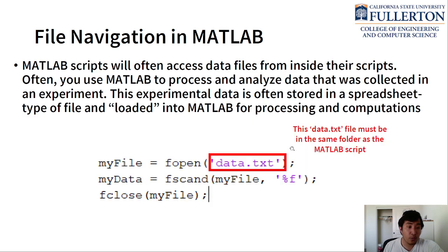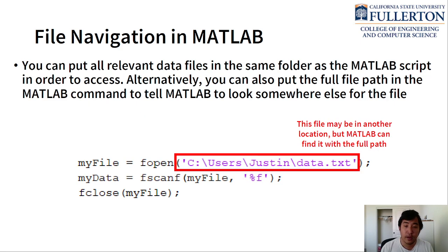Okay. Another place where this is relevant is that in your MATLAB scripts, you're often going to be accessing data files that are outside your script, okay? So, let's say that you ran an experiment and then you save the experimental results in some kind of spreadsheet and you want to load that spreadsheet into MATLAB, right? And so you might have MATLAB commands to load that data. And so in order for MATLAB to access it, this data file, this external file, has to be in the same folder as your MATLAB script, okay? And so if you're telling MATLAB to look for this file called data.txt, that file has to be in the same current folder, okay?